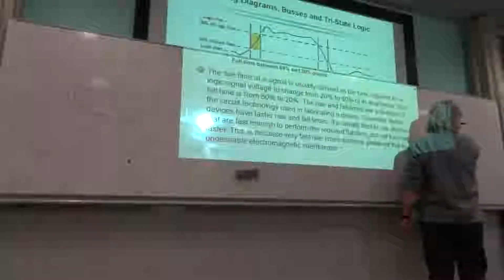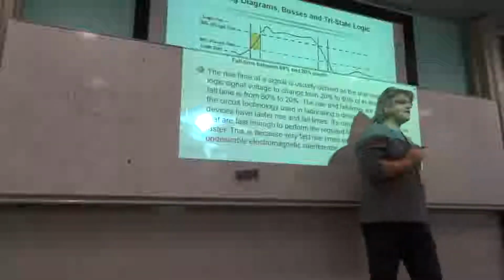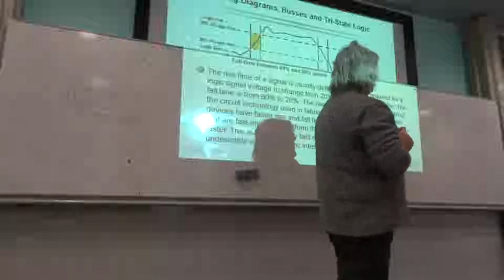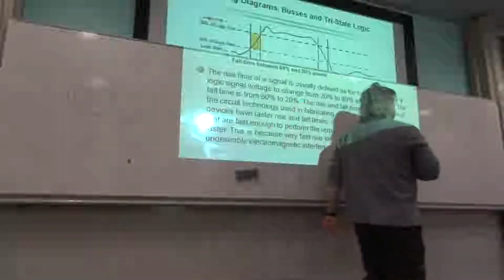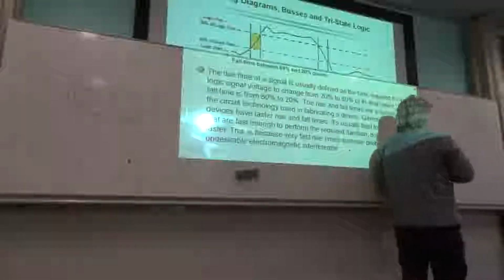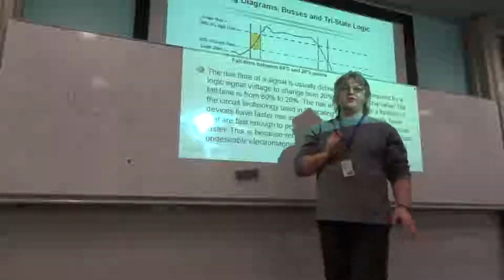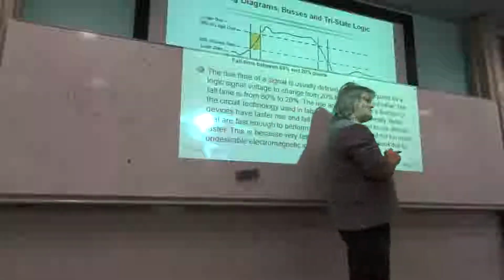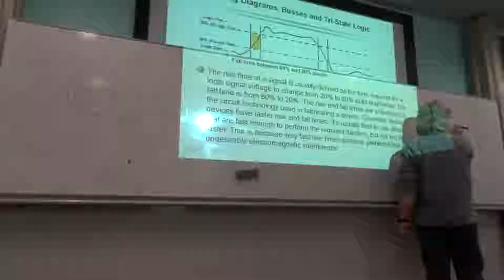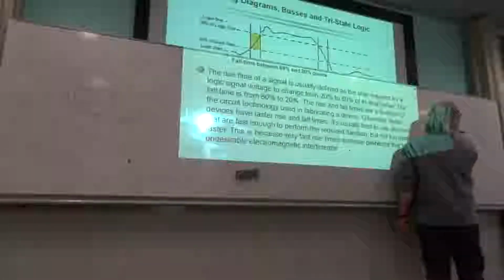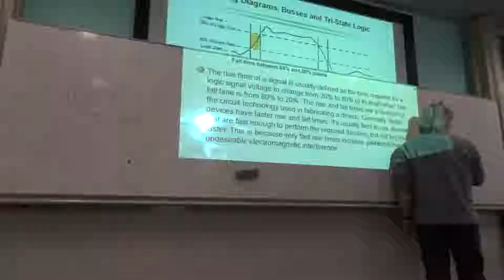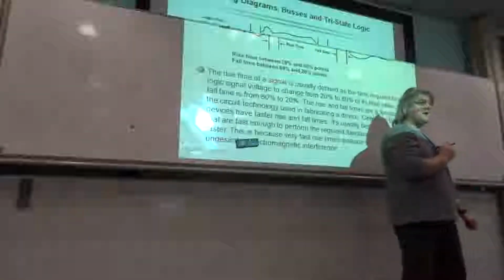There's S, which uses a lot of current, but the rise and fall times are much, much shorter. So often you might see an S part being used in a crystal circuit, straight after the crystal circuit, providing the clock source, high speed. You might see things like HC, which is high-speed CMOS. You might see HCT, high-speed CMOS with TTL-compatible inputs and outputs. And you might see something like F.